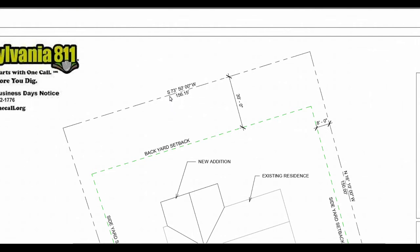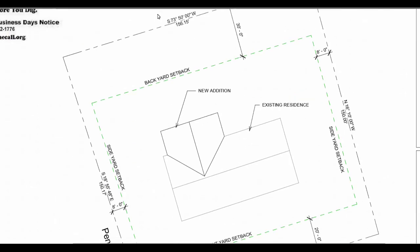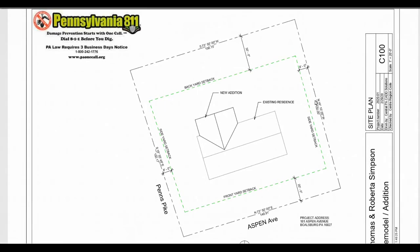The first letter here, S, stands for south, and then the last one stands for west. And if you look at other ones, we have north and west. So this is basically starting at south and measuring 73 degrees, 50 minutes, 0 seconds towards the west. That is our angle. The number down here is the total number of feet, and it's in decimal form instead of feet and inches. So 156.15 feet. So as I go around this complete site plan, I have all those different boundary lines.